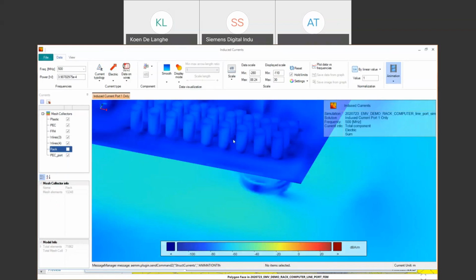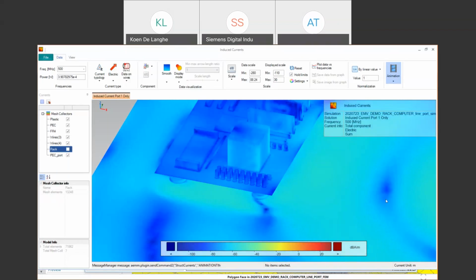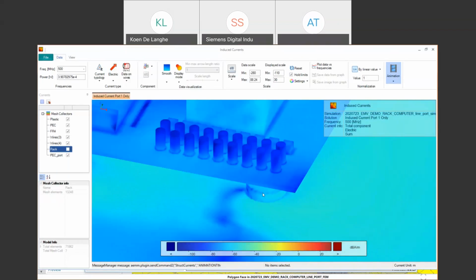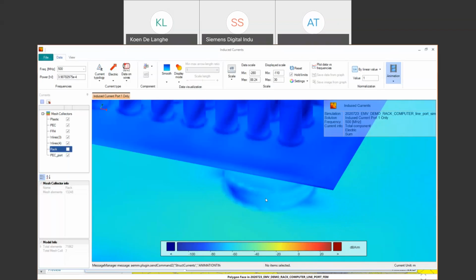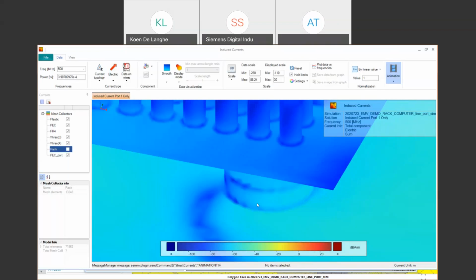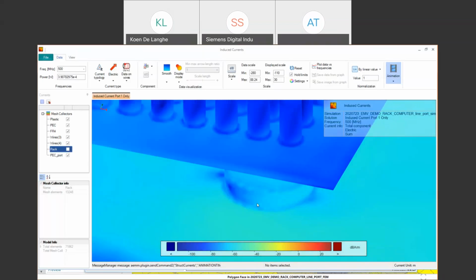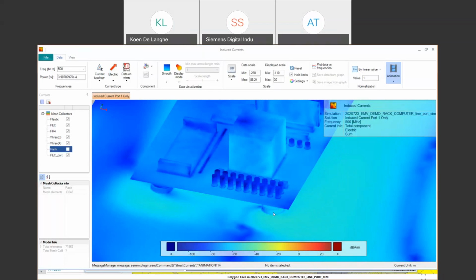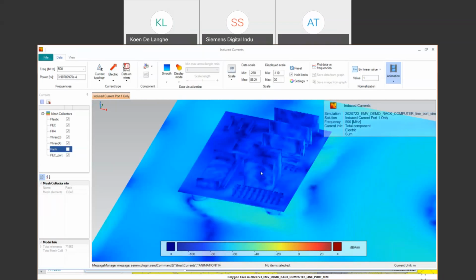You also see, interestingly, the scattering of the wave coming from the antenna with the plastic support. The plastic support is made out of dielectric material, and in the dielectric material your waves are traveling at lower speed. This means that there is some kind of a diffraction effect that you can clearly see here, because inside this dielectric the wave is traveling at a smaller speed.